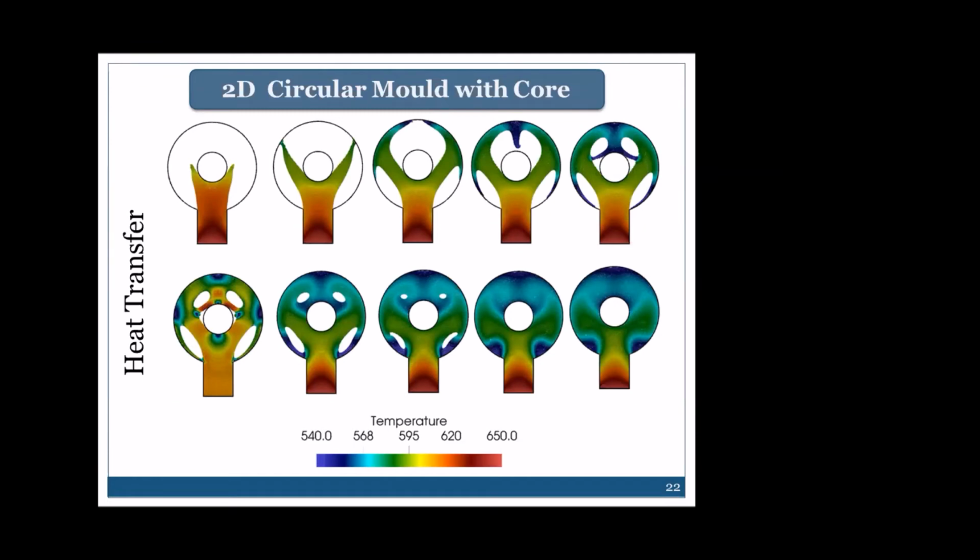So given these results, we can then apply these approaches to simulate our problem of casting. In this slide, we incorporate the coupling with heat transfer and solidification in the classical benchmark example for free surface flow of the circular mold with core. Here it is shown that the temperature evolution is very reasonable and stable during the evolution of the domain, and the cooling behavior is gradually reaching a stationary temperature which distributes in a homogeneous manner in the entire fluid inside the mold, while the temperature values at the fluid in the mold boundaries always obey and keep the prescribed boundary conditions.